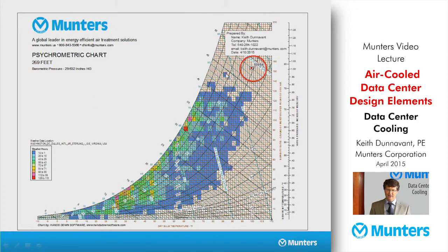During a typical year, this is TMY3 data, typical meteorological year, 3rd edition data, that's been plotted. But you'll see that typical data does not capture the extreme. So I've plotted here the 100 dry bulb and 84 wet bulb condition, just to show you that you have a nice margin of safety if you use this as your design in relation to what is typically occurring.